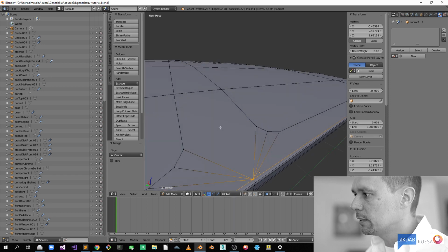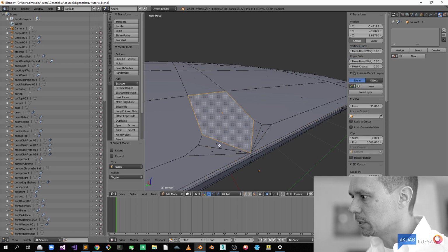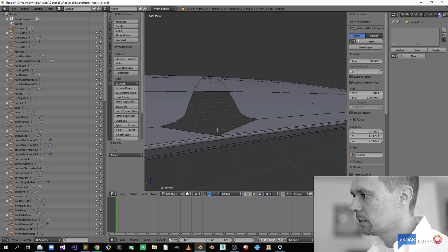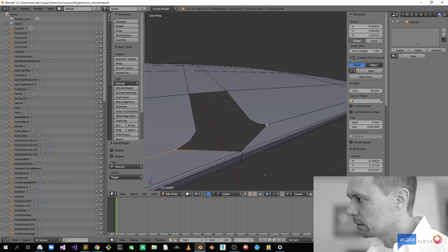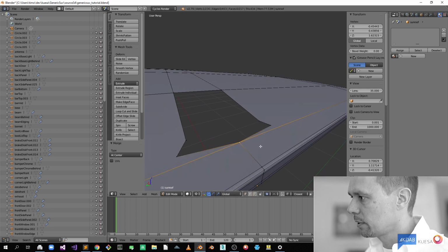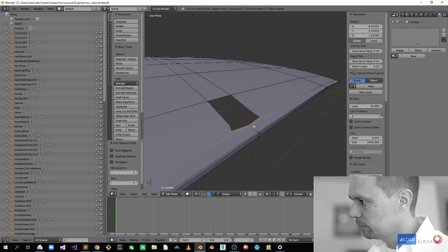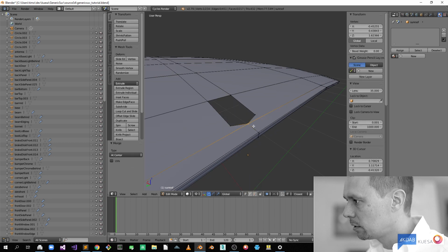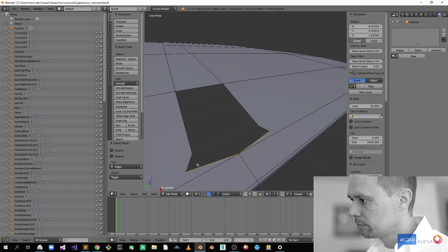So this could be a bit problematic here, so I'm just going to remove the faces and build my own later. So I'm going to select those faces. Remove those. And then I can just collapse those vertices here as I did before. That didn't work, so I need to build faces for this first, with F.